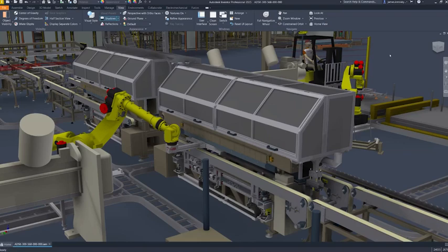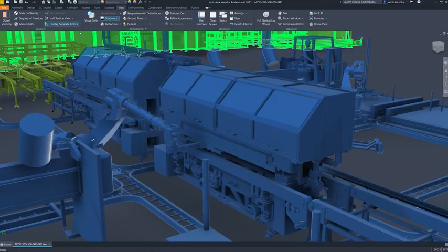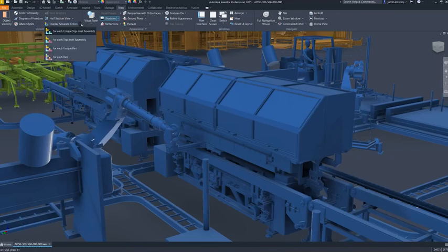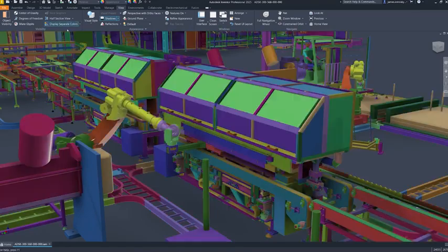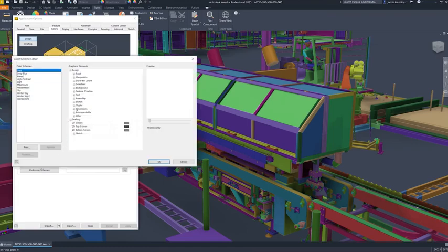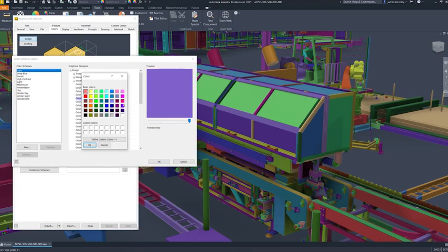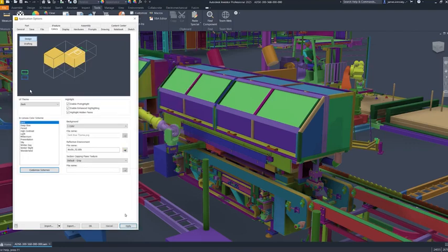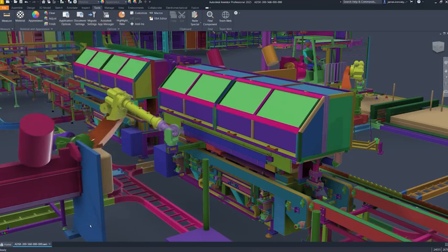We've enhanced our visualization capabilities with the introduction of a new separate color scene display. This can be toggled to various settings and also customized via the color scheme editor of any given in-canvas color scheme. Being a single designer in a 5,000 part assembly can sometimes feel as daunting as being in a 100,000 part assembly. So we've added the ability to toggle colors from a view, tab, or separate top-level assemblies, and then differentiate them between different types of components, significantly improving the clarity of these intricate assemblies. This tool is also compatible with section views and is directly related to efficient management and comprehension of your increasingly complex designs.